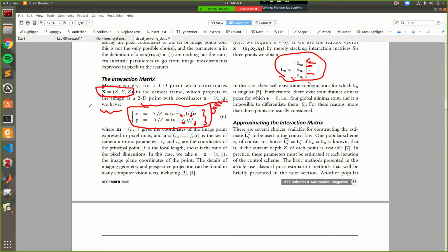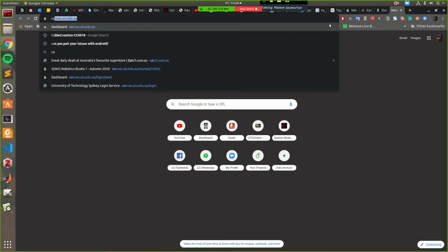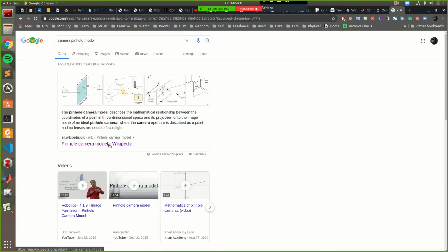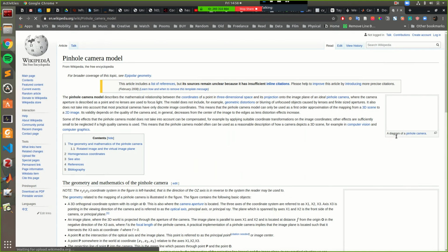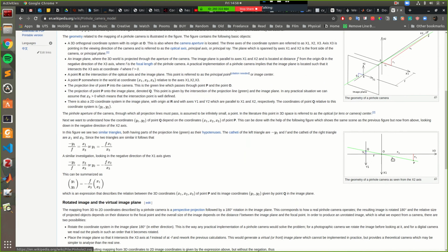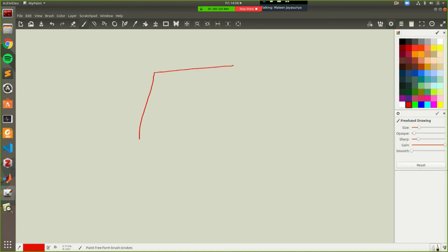No. So z value is with respect to the camera, right? So in camera projection, you need to worry about which reference frame you're looking from, right? So remember in camera projection, Z is this value. Right now, our reference frame is the camera, right? And the camera is attached to the robot, like this, on the arm. So it's attached right here. So the z value is along the camera's principal axis, right?